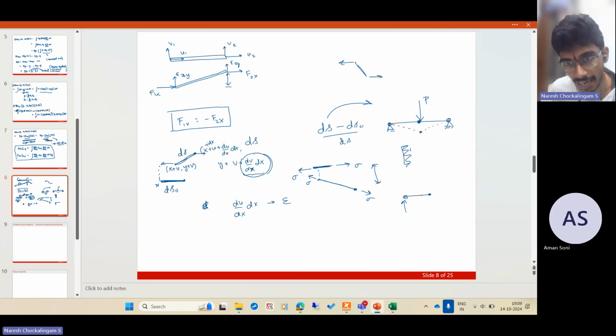So this is an axial force member. This is also an axial force member, but you have to resist a vertical force P at this point. So the net force has to be upwards on this joint. But that is not possible. But the actual reason why you have any stiffness at all is because this is stretching, and that stretching comes from this thing. It's because in nonlinearity, you don't ignore this component. So the strains are defined such that it is change in length by original length. And while calculating the change in length, you consider the vertical deflections also.